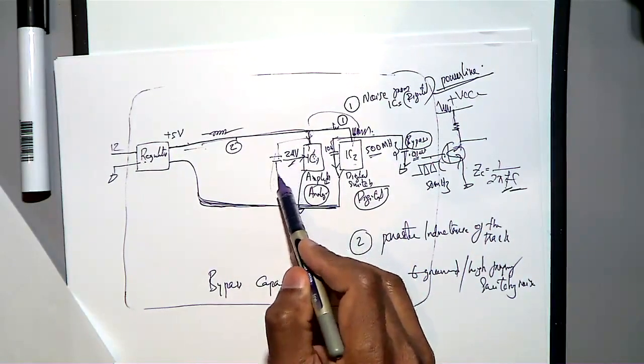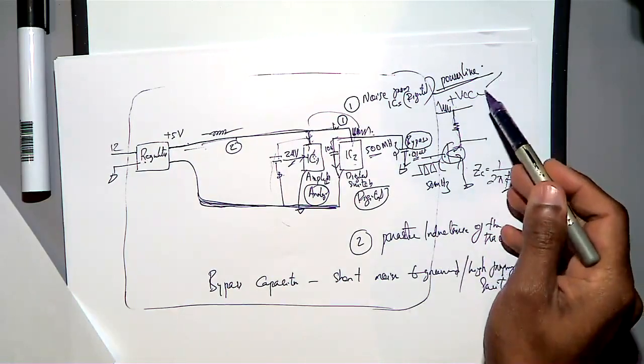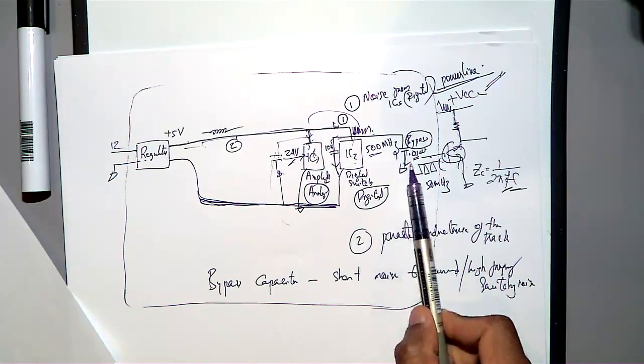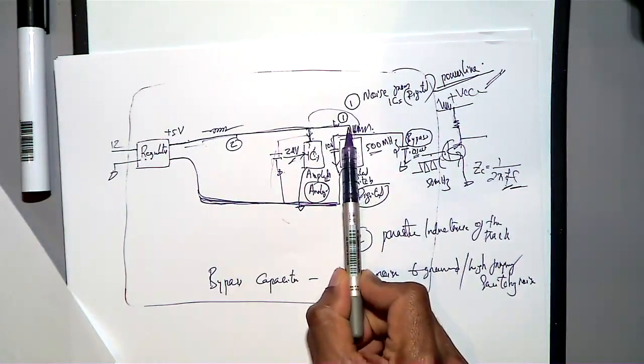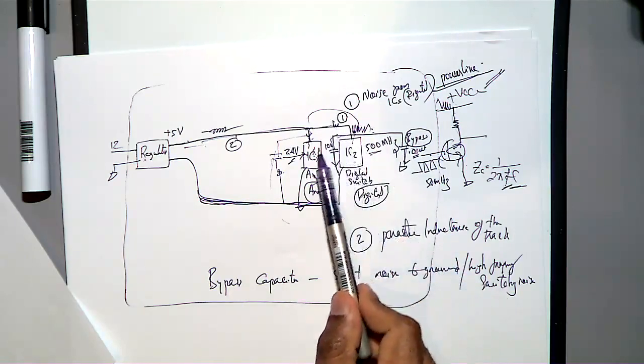Even for analog, people put it. You are putting this to the ground, so that you are grounding all the noises and this part is kind of avoided. But even though you put this much bypass around it, the noise is still not fully suppressed. It can still go to your analog part, because analog is very sensitive. Digital means you have only two levels: maybe 0.5 is your 0, maybe 1.5 is your 1, so you have a noise threshold. If you have 200 millivolts of noise on the digital line, it is not going to affect it because your 0 is 0.5. But an analog signal will be amplified. If noise is coupling and your amplifier has a gain of thousands, it will be amplified in your signal. So even if you use bypass capacitors, you still have to isolate your analog and digital parts.